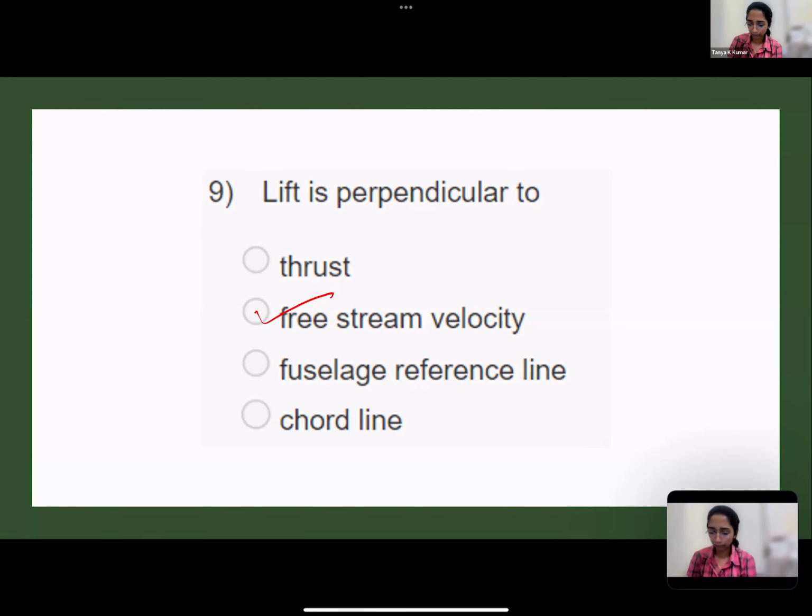All right. So if I keep the engine along, let me just see this. If this is your fuselage reference line, and this is RL, and I orient my engines in this direction so that thrust is produced like this. Now, if your velocity is in this direction, V infinity, then the thrust won't be parallel, it's drag. Drag is always parallel to V infinity.